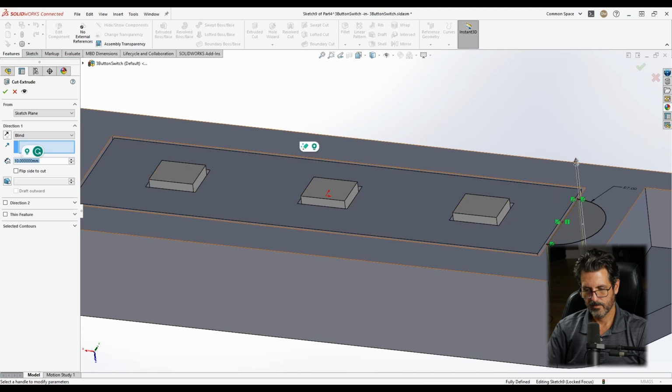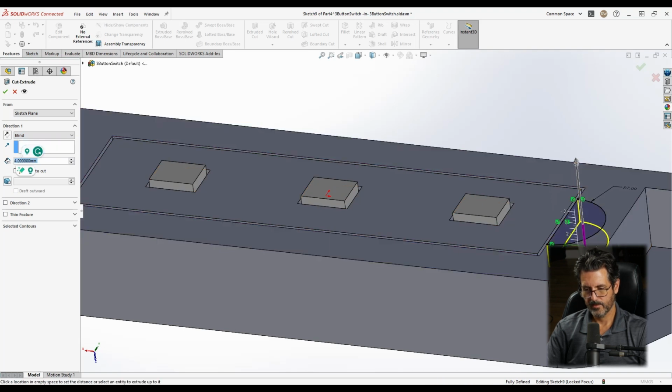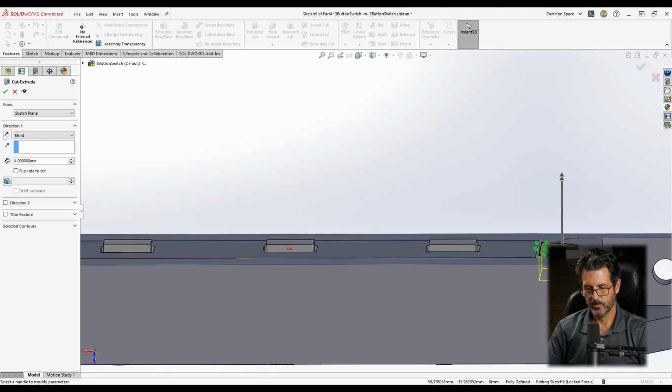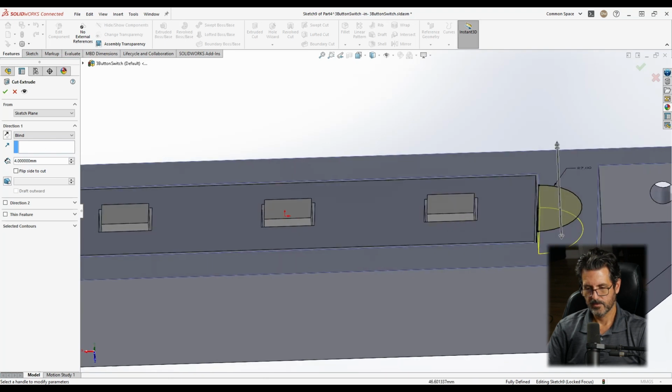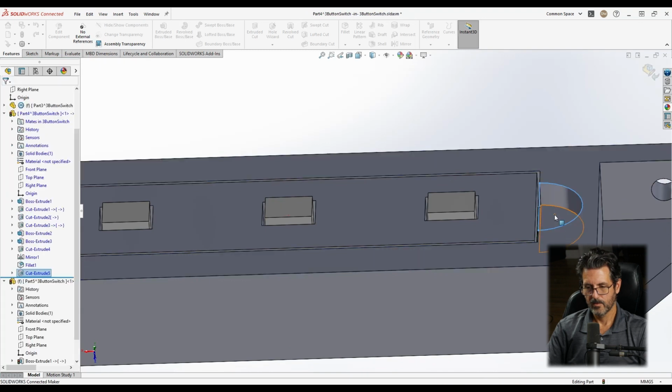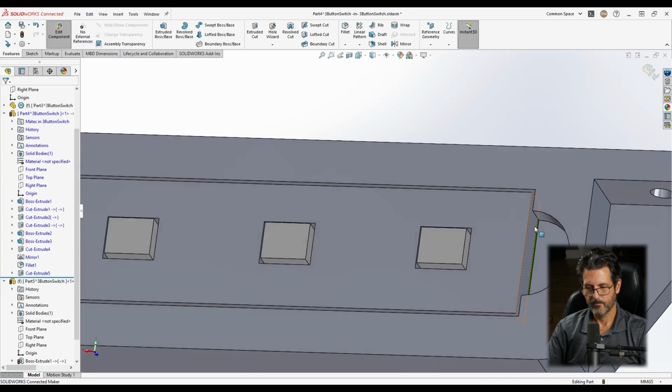If you make it blind, you can drag this around and get a good idea, and then make it more solid. Like there, this is going to give you millimeter increments. So there's 2 millimeters, maybe 4 millimeters. Looks pretty good. Decent size little tab for the ear. Do that. That's good.